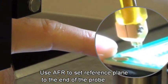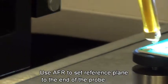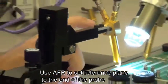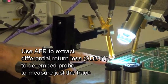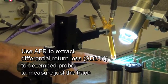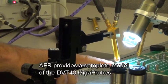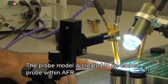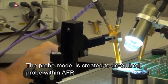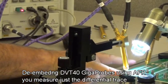So here, we're going to actually use AFR. We're going to derive the S-parameter model of the probe by using an AFR SDD11 measurement. With that one reflect measurement, we're able to get the complete model of this probe and then de-embed that inside AFR and get just the measurement of the trace. Let's show how that happens.